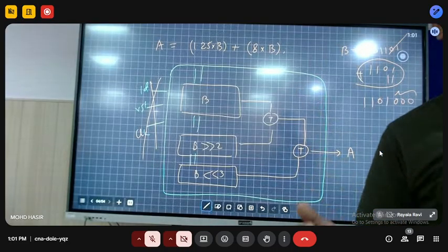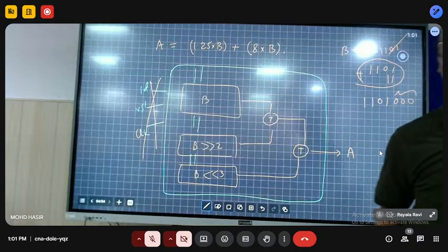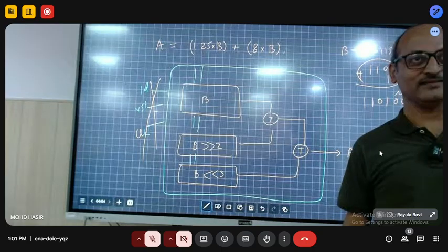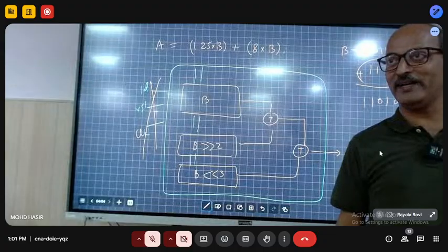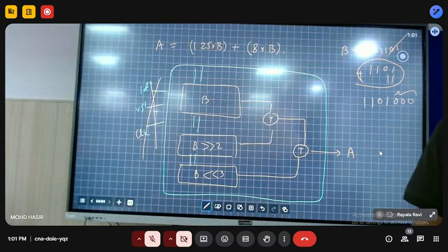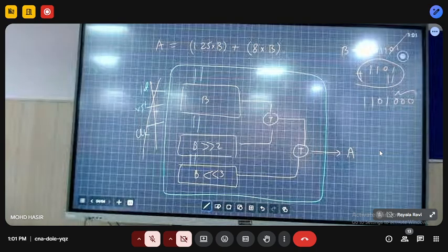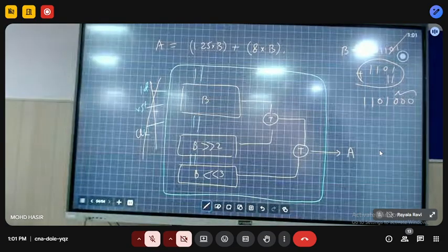Okay, so what will I do? Hard multiplier. Okay, by concatenating these three bits. Okay, and then accordingly by shifting that, I am going to get 0.25. So I'll lose these. Okay, and I know this and the original number together will tell me 1.25. So hard multiplier. Because my goal is not to do multiplied by 2, multiplied by 4, and then come to multiplied by 8. Why am I increasing my critical path and hardware?